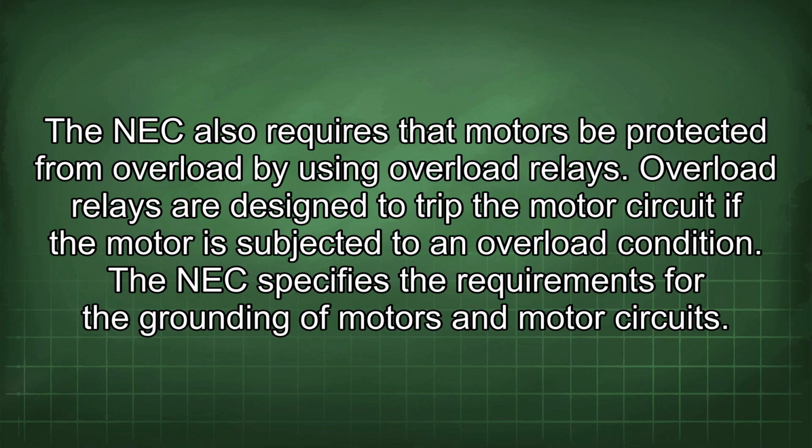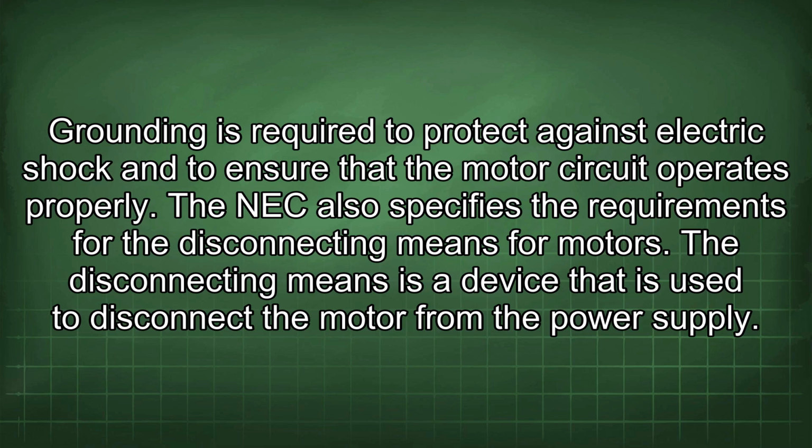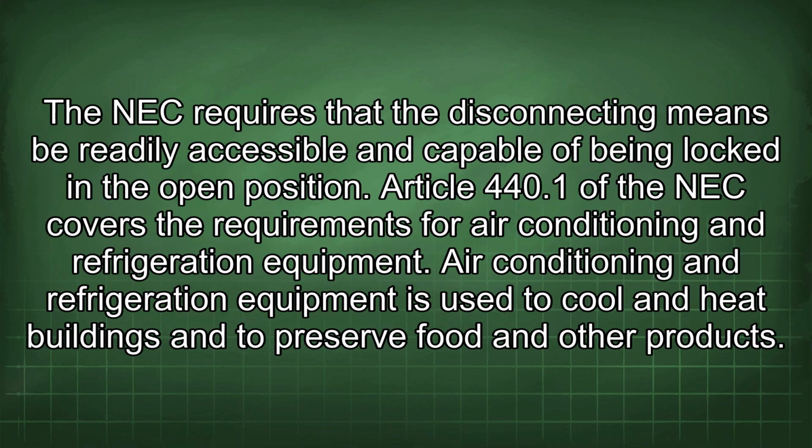The NEC specifies the requirements for the grounding of motors and motor circuits. Grounding is required to protect against electric shock and to ensure that the motor circuit operates properly. The NEC also specifies the requirements for the disconnecting means for motors. The disconnecting means is a device that is used to disconnect the motor from the power supply. The NEC requires that the disconnecting means be readily accessible and capable of being locked in the open position.